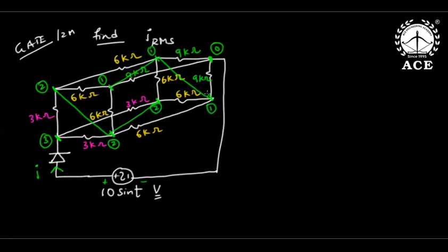That is the trick. So here though resistors are not equal, now you see the path resistance from 3 to 0 in all paths is equal. You always travel from high potential to low potential: 3, 6, 9. So everywhere the path resistance is equal. The trick is though resistors are not equal, the path resistance in all paths is amazingly equal. So you can do current division and write KVL, or the direct shortcut is to join such nodes which are at same potential. I use the second trick which is faster.